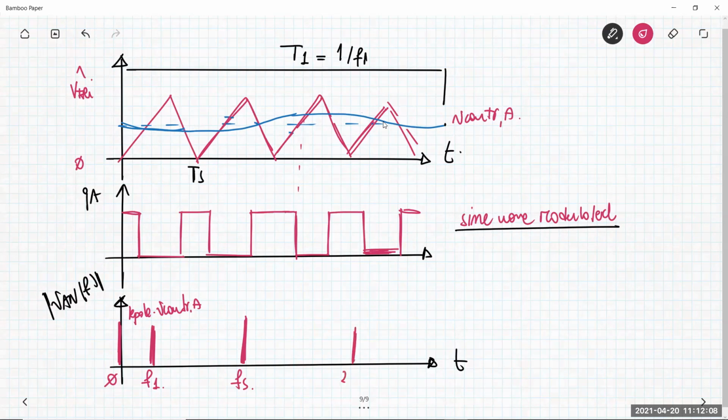Then you can have harmonics, okay? And then you have something that appears that are intermodulation products, like this. You have some side bands. Okay, the difference here between the different lines is exactly F1. So you have the difference is always F1. So F1 is the frequency of the sine control voltage here. And then you have all these intermodulation products.